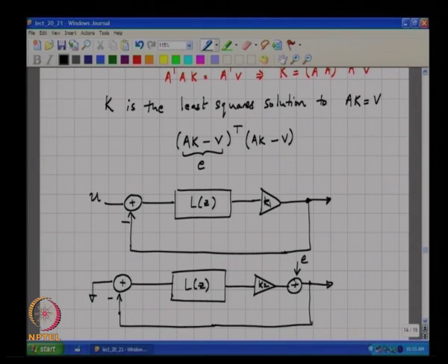The motivation for breaking it up into these two systems is simply that you represent the quantizer by a block which is giving one gain for DC and another gain for the noise plus adding an error, right. What is responsible for the noise?